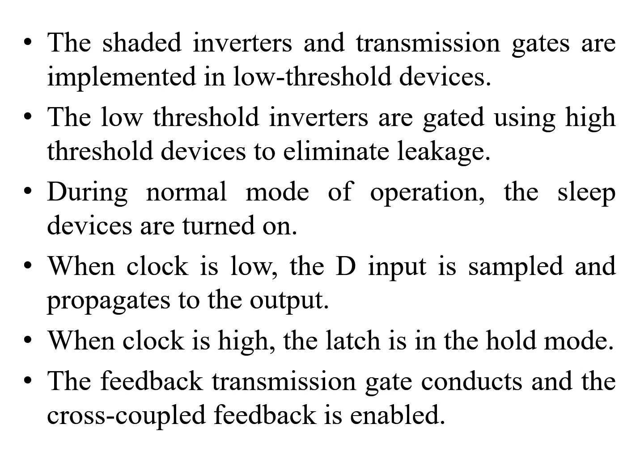The shaded inverters and transmission gates are implemented in low threshold devices. The low threshold inverters are gated using high threshold devices to eliminate leakage. During the normal mode of operation, the sleep devices are turned on, and when the clock is low, the D input is sampled and propagated to the output, and when the clock is high, the latch is kept in the hold mode.